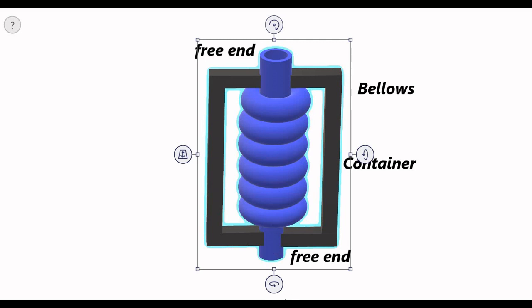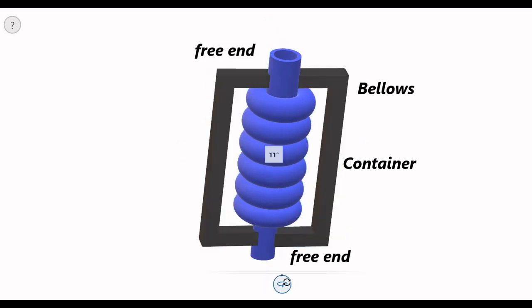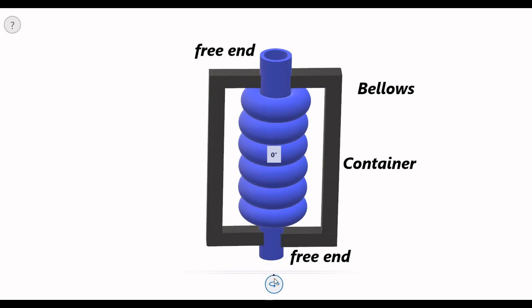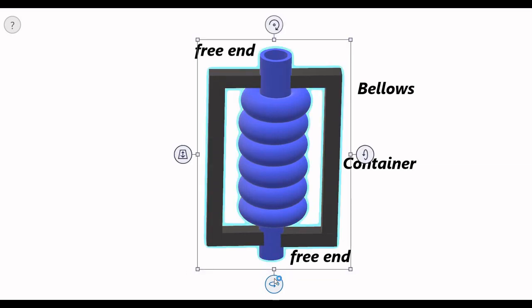As you can see, this is an elastic cylindrical structure with a number of convolutions or corrugations stacked one above the other, with two ends, one end connected to the source of pressure, another end free to move, which is connected either to a pointer scale arrangement or a secondary electrical transducer.